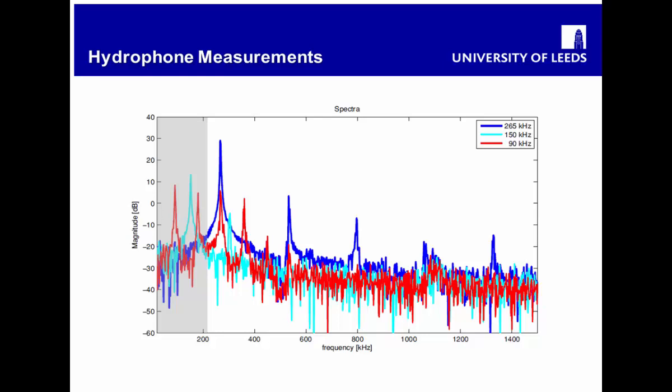Okay, first thing, I plotted the spectra because I want to characterize the nonlinearity of the system. It's not easy to characterize the nonlinearity in the time domain, but if you go to the frequency domain, you can analyze the harmonics and comment on the nonlinearity generated by the system. So I'm looking at the 90 kilohertz one here, the red one. I can generate up to the 6th harmonic above the noise level. It's quite nice, it's a nonlinear system, but it's nowhere close to a megahertz range. It's not going to be helpful for any biomedical application.